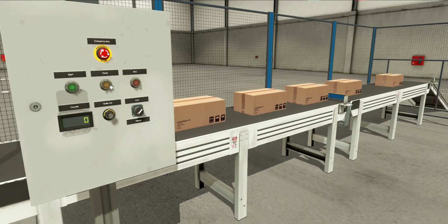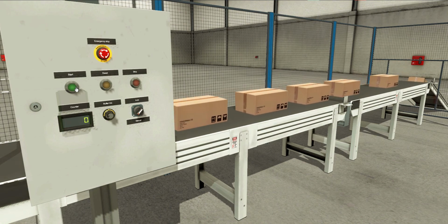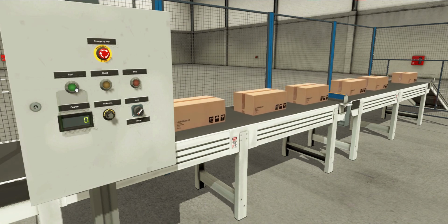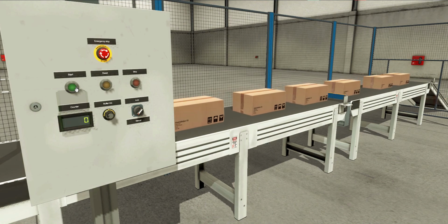Finally, we can observe the complete operation of the control panel, where some bad manipulations of the function are simulated, and how the emergency button works by disabling all other functions. In this way, until this button is deactivated, the mechanism of the machine will not work, preserving the safety of the living beings that are around, and also the integrity of the machine.